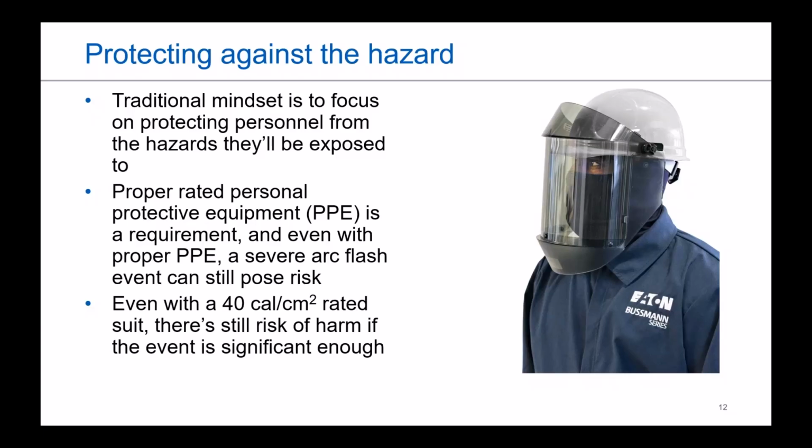You may have protective eyewear on, but if that flash is bright enough and you're looking directly at the source when it occurs, there's still a chance you wind up with some eye damage. There's still the concussive force that can occur, along with shrapnel. These are things you can't really protect against with PPE unless you were wearing almost the same kind of suit used to disarm a bomb. And even then, there's still risk even with those suits.